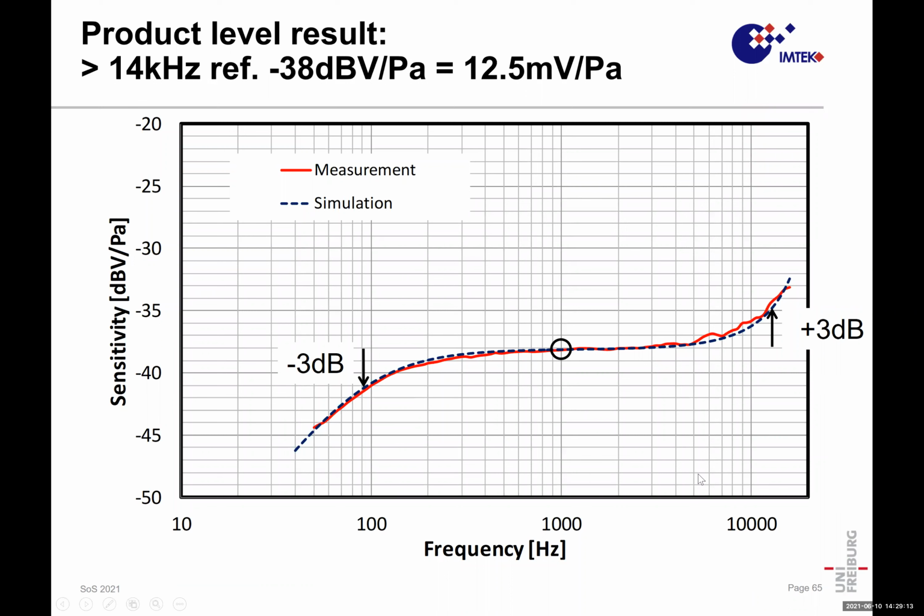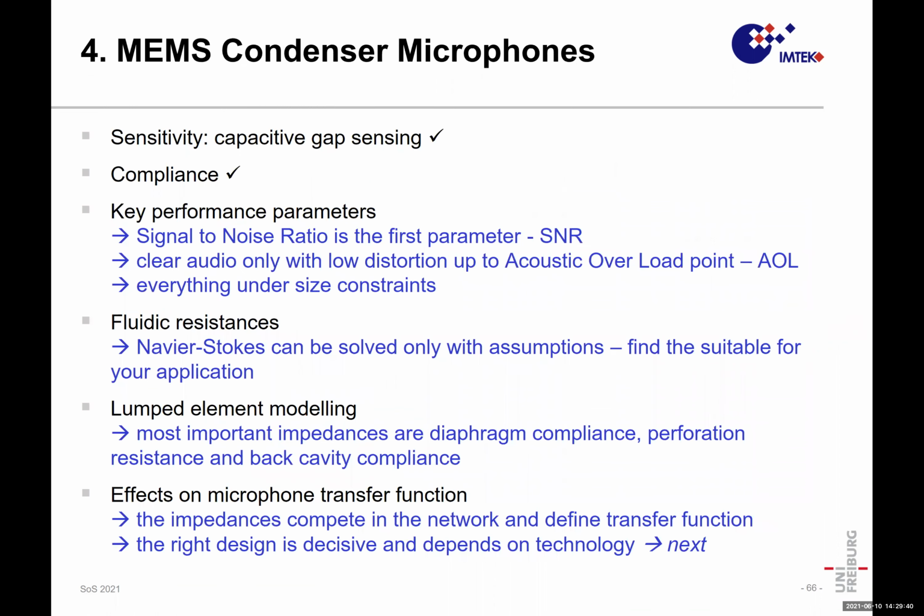We have in red real measurements of a typical device and the simulation of the frequency response of that respective model. It fits the corner frequency of the ventilation and package and so on quite well. It fits also the emerging resonance of the package situation. And of course, we are happy to predict this, and it's quite fair. Yeah, with this, I want to end this lecture.